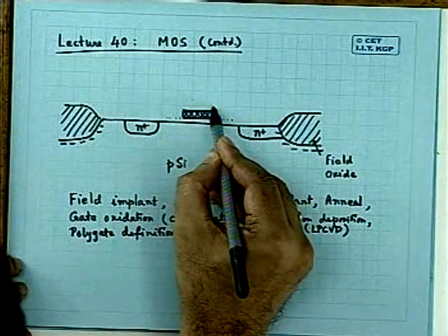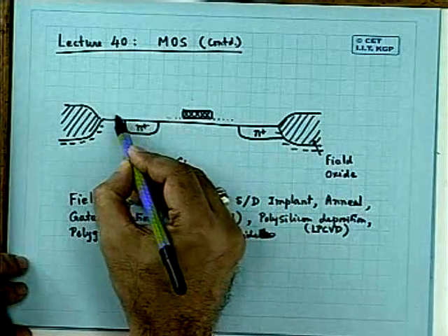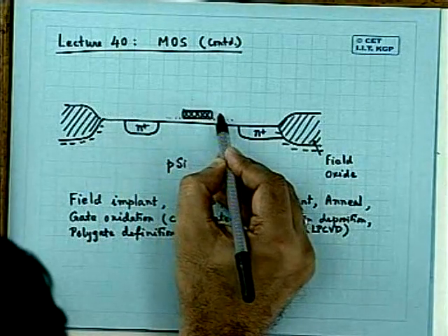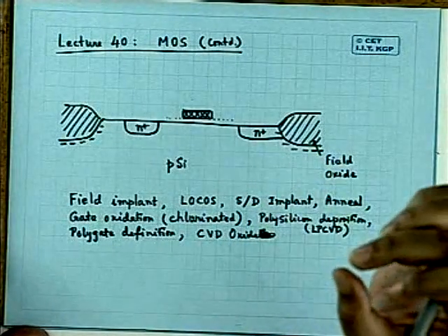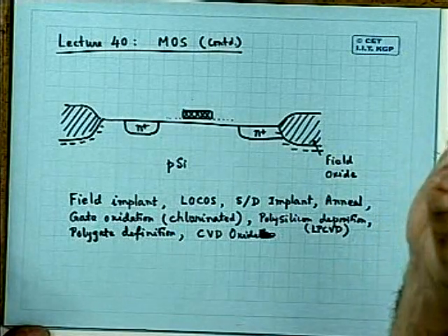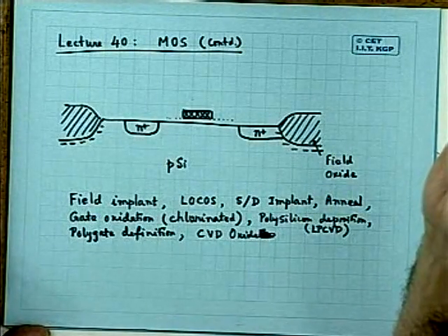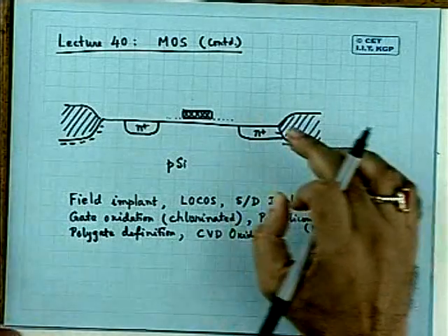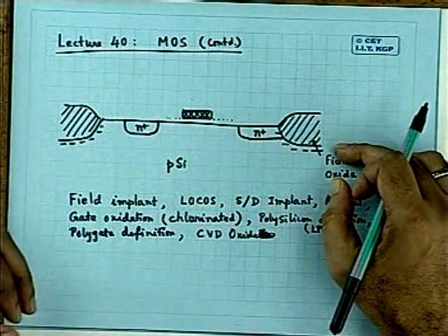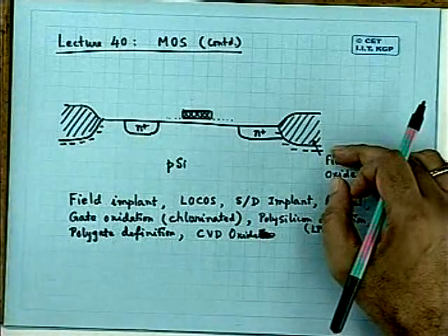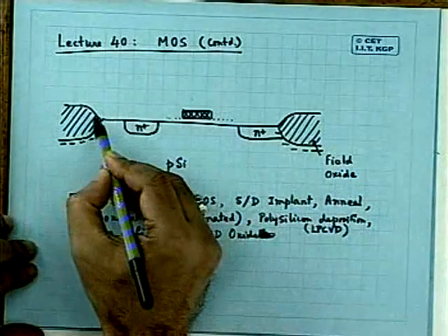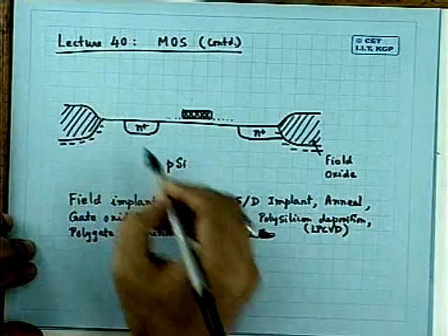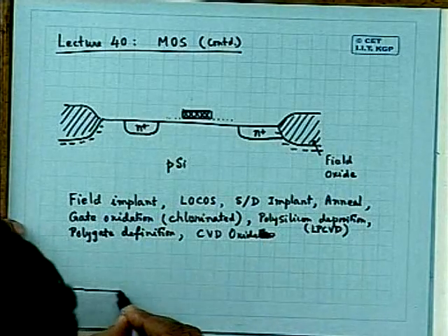Okay? And this silicon dioxide, which is deposited like this everywhere, is of much thicker value. It is rather easy to grow a deposited thickness of around 2-3 micron without much difficulty by CVD process. Whereas if it is a growth process, oxidation of silicon, it takes a lot of time, but you get a better quality oxide. Okay? But in this case, intentionally we use a thicker oxide with good coverage like this. I can show you here, not on the main design.